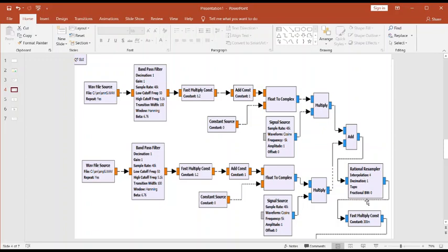Now, the transmitter values have to be in the range, the samples essentially have to be in the range of 1 to -1. So when you do all this multiplying and adding, you're going to create your stream, and if you simply plot it, you're going to see that the max and min go greater than 1 and less than -1. So that's what this multiply by 0.3 down here is.